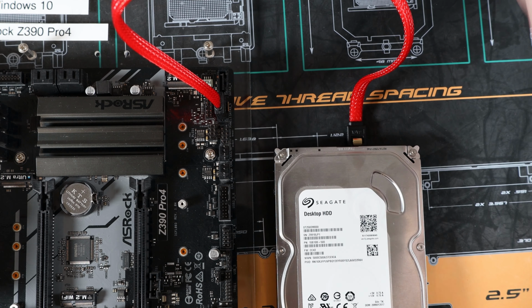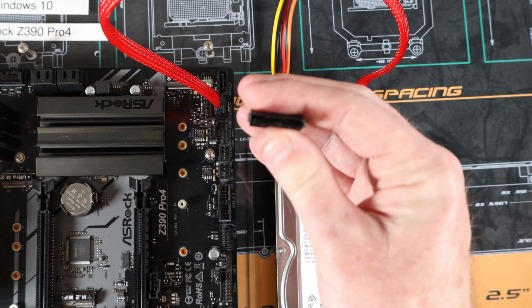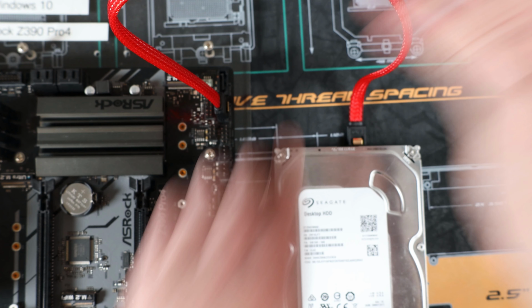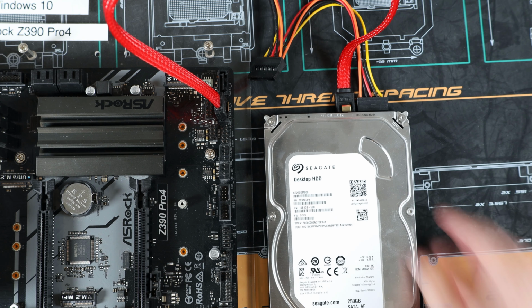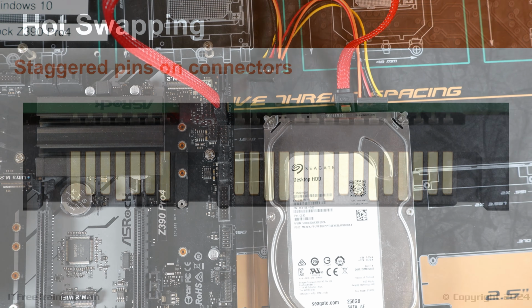The next step is to plug in the SATA power connector. As before, the SATA connector is an L-shaped connector, so in order to plug it in, you just need to make sure that it's up the right way. That's really all there is to it for plugging the connectors in. The computer's off at the moment, but I have plugged the hard disk in while the computer was on. Let's have a closer look at how the connectors support hot swapping.